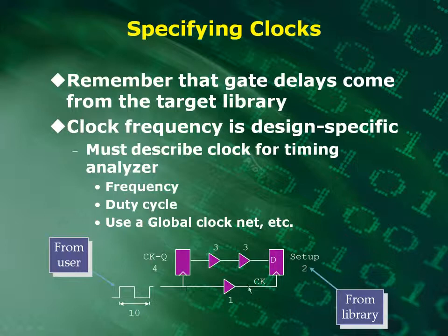You may even have clock delays too, but the tool will calculate all of that for you, so long as your flip-flops are running on the same clock. All of this information comes from the vendor's library for the particular FPGA part you're using. So it does all this work for you.